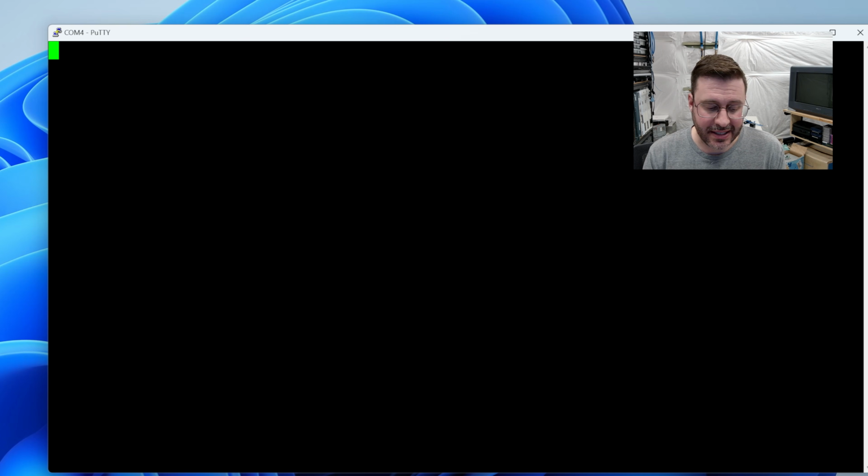I'm going to type AT, and it said okay. Notice I can't see what I typed. The modem hasn't been configured to echo back to me. Let me go look up how to deal with that. I'm going to type ATE1, ATE1. And now we can see my AT commands.